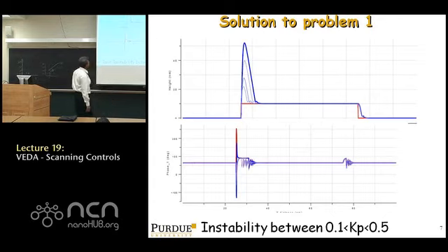Okay? The different curves correspond to different amounts of proportional gain. The very top solid blue line corresponds to the smallest proportional gain. As you start cranking up proportional gain, you can see that the overshoot you're getting is starting to decrease. What I haven't shown here is that at the highest value of proportional gain here, which leads to very small overshoot, if I crank up the proportional gain just a little bit more beyond that, you get unstable motion. It just goes crazy.